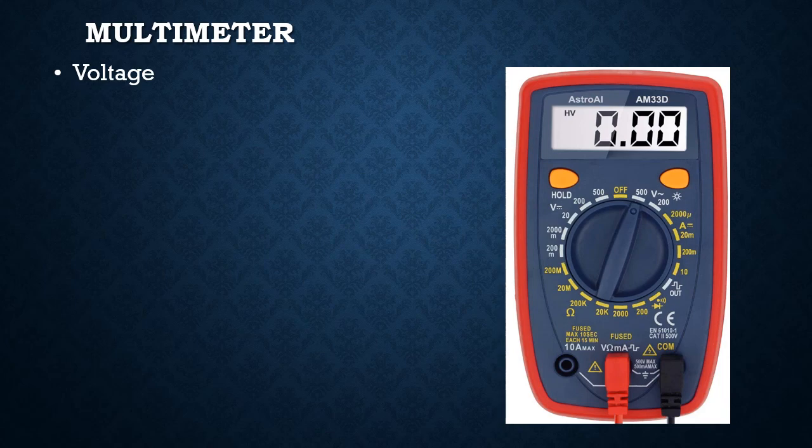So when you find your multimeter, the first thing you want to make sure of is that it's in the off position, okay, which means that the dial is turned to this yellow mark up here. But we'd like to use it as a voltmeter first. You need to put your leads in, the black lead into the COM port and the red lead into the center port. You need to make sure that you press them in firmly so that they're fully inserted into these ports.